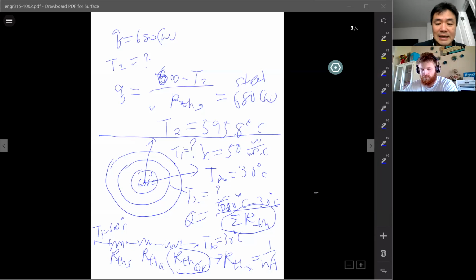Okay, this is where we were last time, right? We had an example here where you have 2 layers of conduction. Then you have the convection outside the outer layer, and the overall thermal resistance for this serial arrangement just equals the resistance of the 2 solid layers plus the resistance of the convection air. Okay, and remember the formula of the thermal resistance, right?